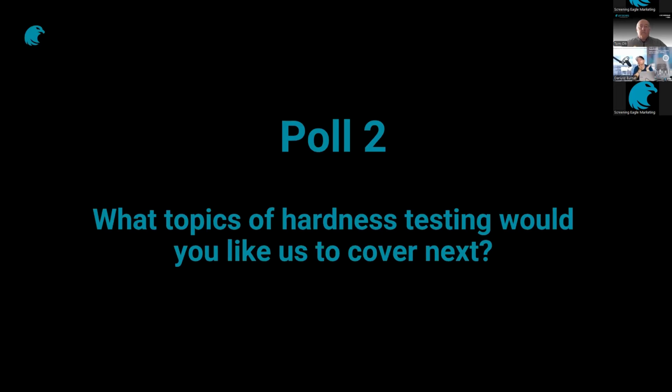What about flapper discs, Tom? Do you have any experience? I recommend flapper discs personally. With the lovely portable technology and battery-powered angle grinders, a nice flapper disc with the sandpaper flaps works very, very well, because they not only remove the material for the surface preparation, but they actually self-cool because of the individual pieces of sandpaper rotating around.